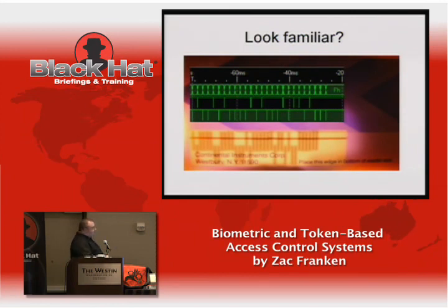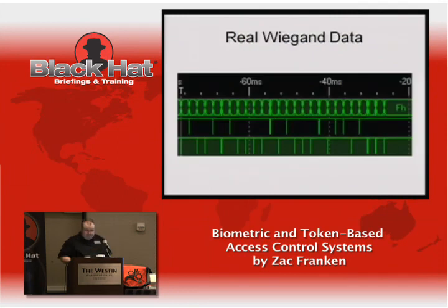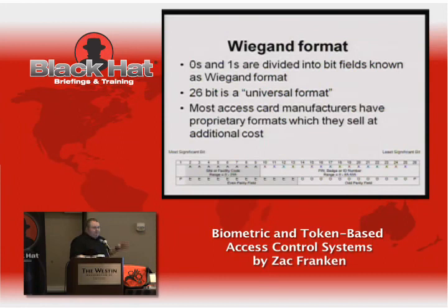There were 2 sets of sensors, one reading the 1s, one reading the 0s, and as you swipe the card through the reader, that little 40 microsecond dip was the little pulse of energy given off by the wire. So we've got the actual card itself, we've got the electrical protocol, and this is what's actually sent down data-wise.